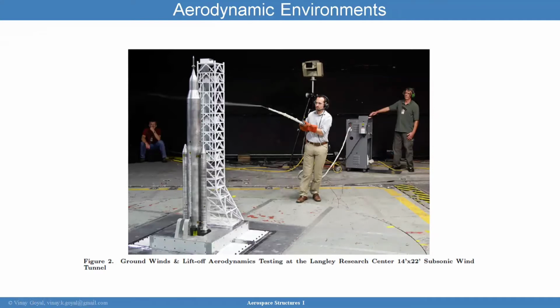I want to go a little bit back and discuss a little bit more about this wind tunnel testing. So, in essence, you will get a flow visualization technique, and you can look at how the flow is moving through this part. The testing can help you determine the vehicle bending moment, and it can provide you the integrated forces across the vehicle.